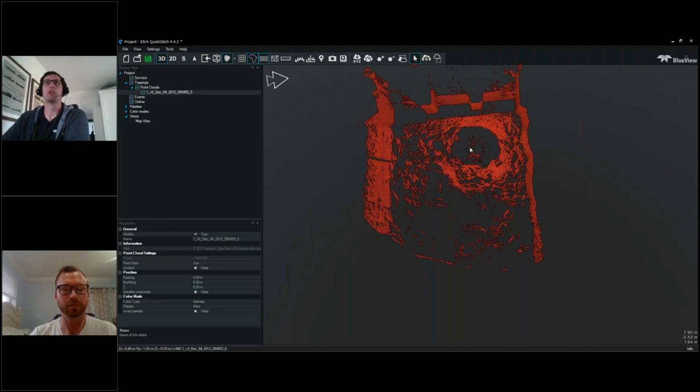What we'll find as I bring in the other scans is that there are 4 locations. So there's scan location 1, scan location 2, 3 would be about here, and 4 would be here. So presumably that would be written out on a map during acquisition so we know which location corresponds to which area. This is kind of a small area, so it's not too hard to figure that out, but on larger data sets with more locations, you'll definitely want a good scan location map.